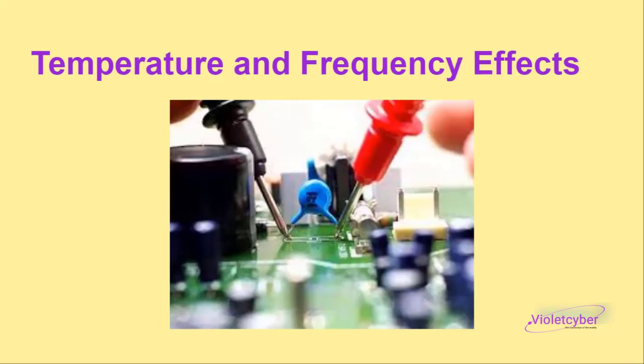Temperature and frequency effects. Ceramic capacitors exhibit significant changes in capacitance with varying temperatures and frequencies. For timers or oscillators requiring high stability, use capacitors with an NPO temperature class, which minimizes capacitance change with temperature. For high-frequency circuits, capacitors with good stability at high frequencies, such as mica or film capacitors, are recommended.